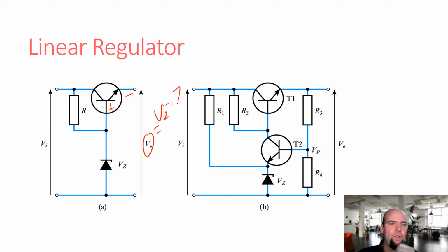So we're going to have this voltage drop across the BJT, and so it's a little off from the Zener reference, but whatever, we can choose it appropriately. The main thing is we're going to use that amplification of the transistor to improve the efficiency this way.